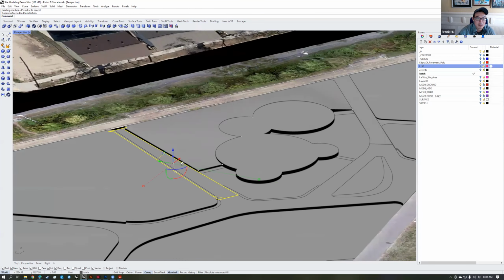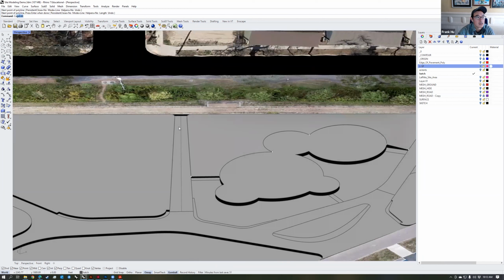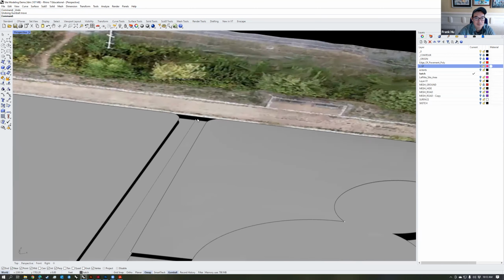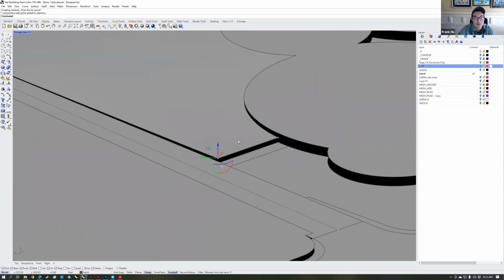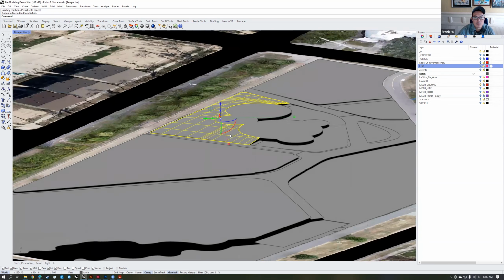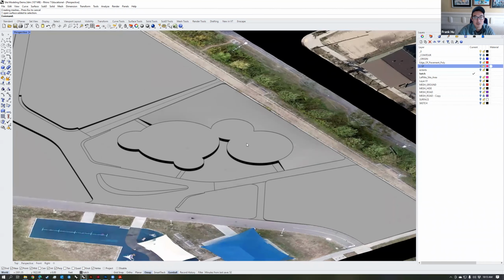Let me do this path here. In this case, I'll demo the cage edit with a reference geometry one more time. With this path here, you draw a reference curve from the midpoint of the base to the midpoint of the top, type in cage edit, and select the captive object, which is this here. You select the control object here, then choose global. Now you can manipulate this path in this method. So this will just do M, V, move that up to the nearest vertex. Now we can take this portion here, M, V, move that to there. Hopefully you see that's how you can begin to model landscape to match your elevations of features.